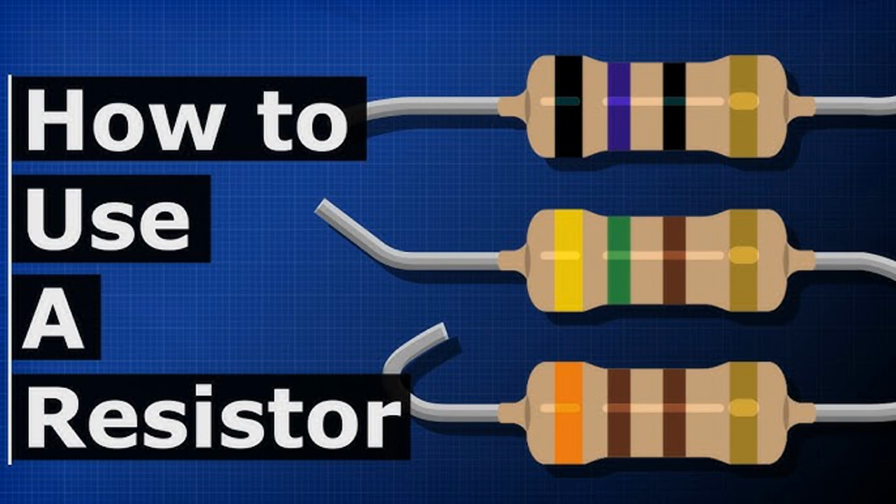Types of biasing. Voltage biasing involves applying a constant DC voltage to a terminal of the device. Current biasing involves applying a constant DC current to a terminal of the device. Biasing in bipolar junction transistors, BJTs. For BJTs, biasing is crucial to ensure the transistor operates in the correct region, active, saturation, or cutoff, depending on the desired application.